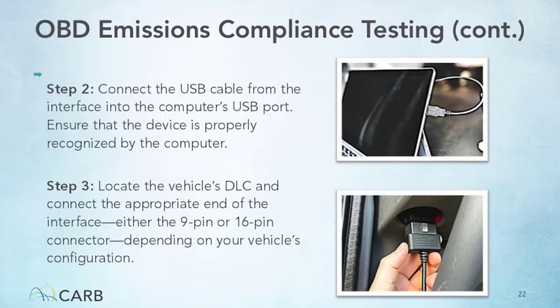An account with login information should be established through your device's vendor. As shown in these pictures, connect one end of the testing interface to the computer's USB port and the other end to the vehicle's DLC. Pay attention to the type of DLC as explained earlier in this training.